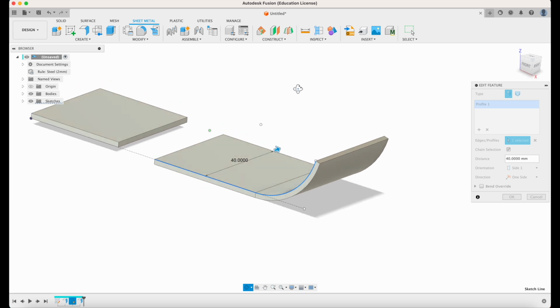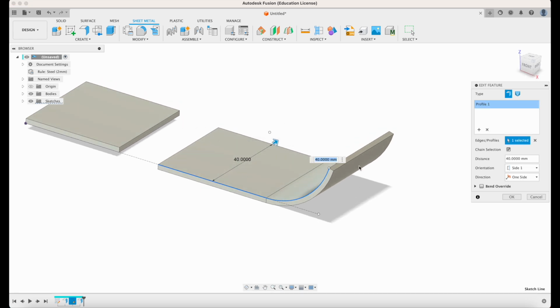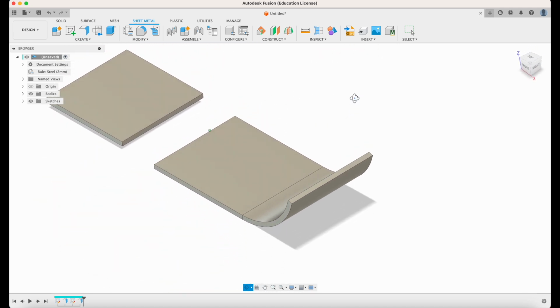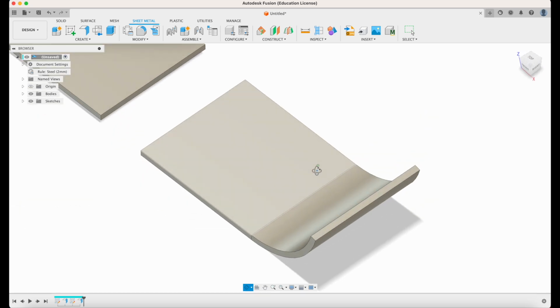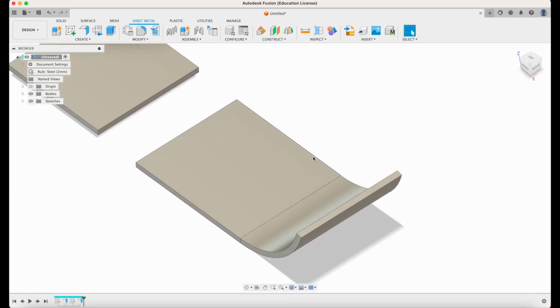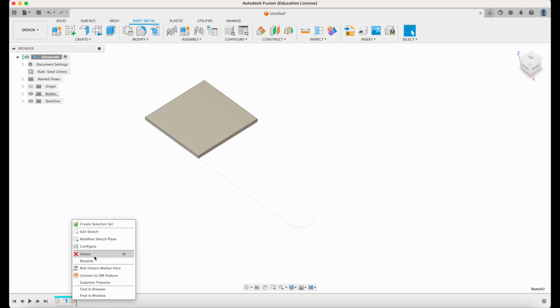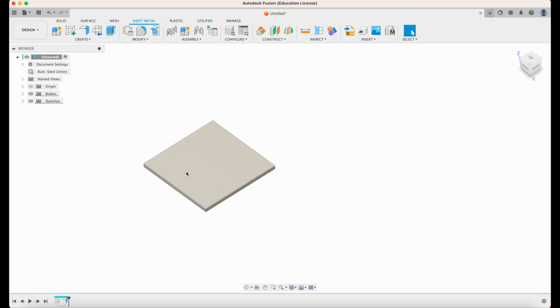As you can see, the 2mm sheet metal rule that I applied is also applied for this. You can see the rule right here on the left-hand tree. It says rule sheet steel 2mm, and I can say okay. Now, this is also a sheet metal piece, so you can start with a bent piece as well. Now I'm going to get rid of this example so we can concentrate on our first flange.